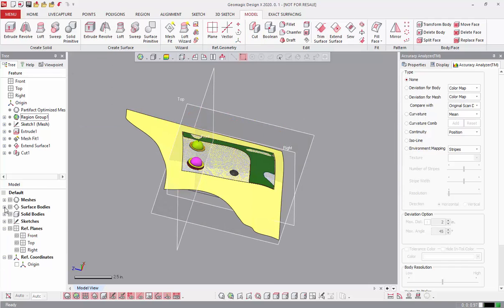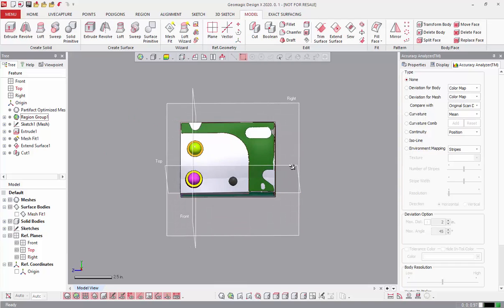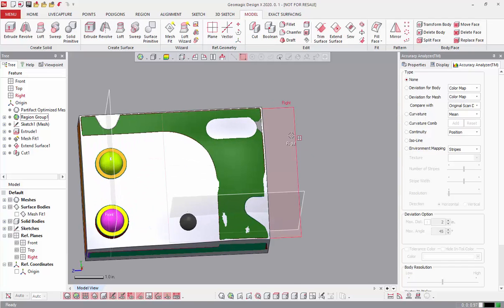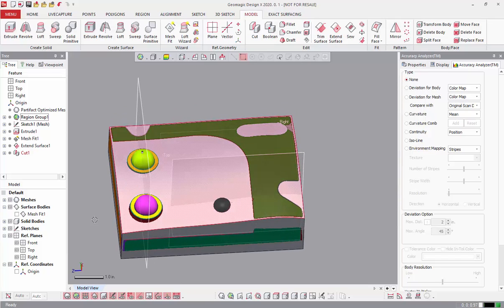And so here's actually the reason that I wanted to make this video in the first place. I had a customer ask me about a portable CMM arm. They are trying to probe hole locations all over a large car, essentially a vehicle chassis, and they're having some struggles with some workflows inherent to that, unfortunately. So what I recommended they do is just scan the top of the surface so that they can see where there is scan data and where there is no scan data, and they can use some of the mesh sketch features to figure out where that whole location is.